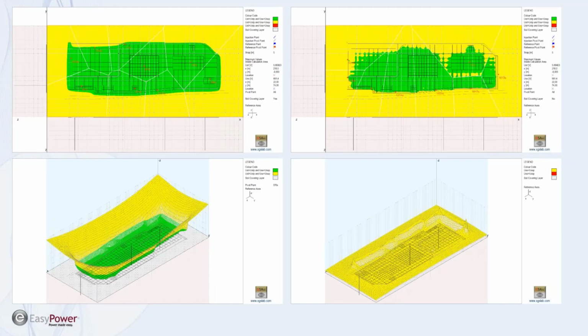The step and the touch allowable voltage are calculated per the IEEE 80 equations. Starting on the top right, you can see that these are kind of small, but top right is an example of the safety calculations for both step and touch in that grid without any surface covering applied. So standing on bare native soil. You can see that the USSP on the top right is step potential, USTP is touch potential. The green areas represent where both are below the IEEE 80 calculated danger condition, and the yellow indicates where your step is safe but your touch is not safe.